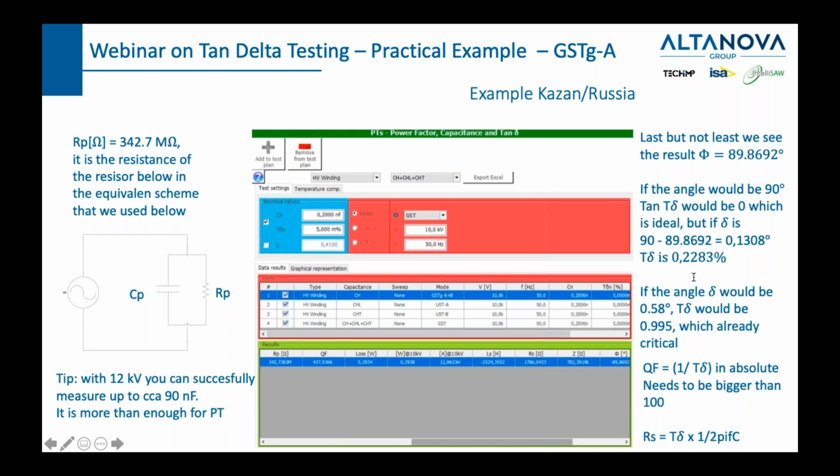You generate on the phases, you measure from the ground, you do a tip up and a tip down test, and you see if the tan delta is below 3 or 5%, depending on what type of insulation you have. And sometimes you just need to do a tip up and a tip down test and not even look at the numbers so much. But when I say look at the numbers, compare them with some values, you need to see if at the same voltage level, they are the same when you are going up and when you are going down.